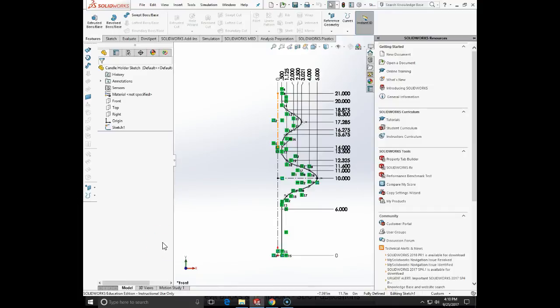Hello, this is the example from page 1116, where we are going to use two surfaces to create the intersection curve. The first will be a revolved surface, the second one will be the sweep surface made around the spiral. And then we are going to create an intersection curve and create the solid sweep around the intersection curve, which we are then going to array to get our beautiful candelabra.